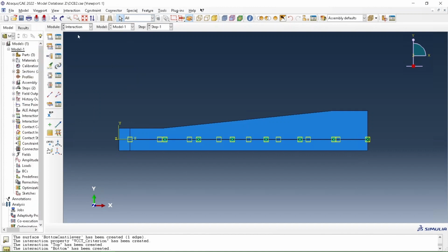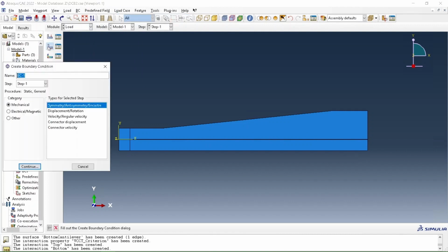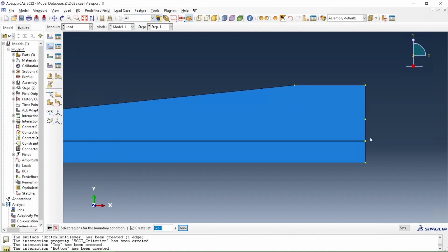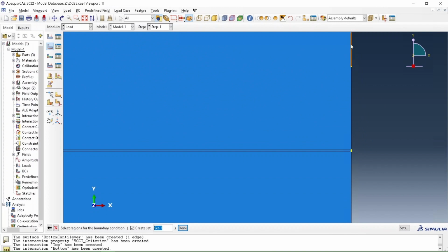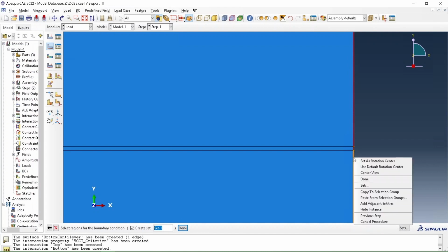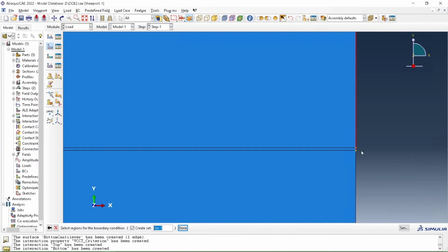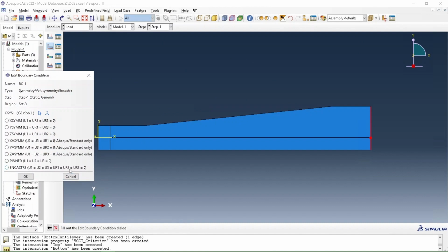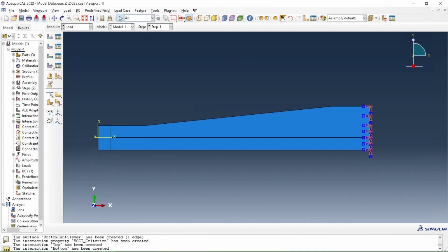It's nice. Next, I want to define loads. Before that, I'm going to define my boundary condition, of course. I'm going to press continue here and dismiss this because I want to select my boundary edges manually. I have shift pressed down and I have selected 4 edges over here, and I press down and I encastre these edges.